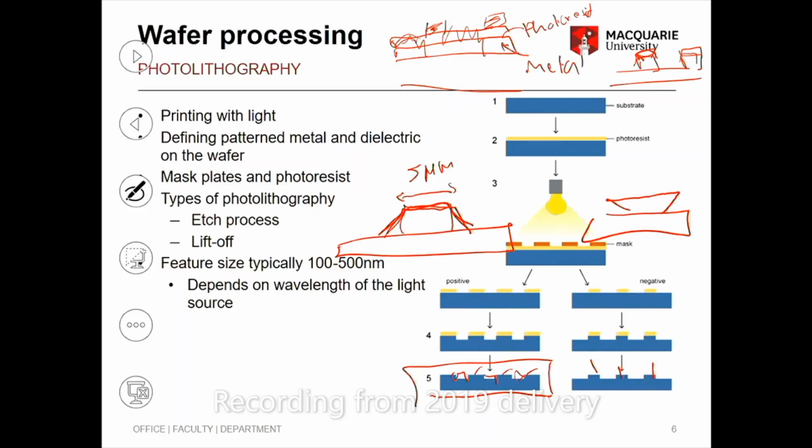Once you do all your layouts, you do something called design rule check, which is called DRC. In the DRC, if you are lower than 5 micrometers, it'll be picked up, and they'll say there's a design rule error.